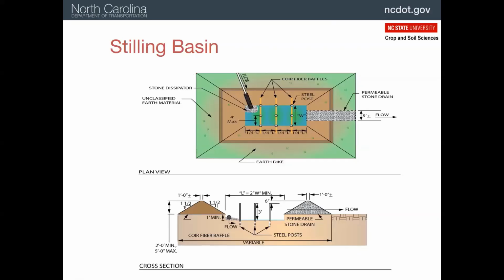Bird's eye view, so we're pumping the water and making sure that that is also released so it doesn't erode the inside of that stilling basin. And then we have an over excavation, so it's a foot deep here. So the water has to rise up a foot and then goes out through the stone. So that's our stilling basin concept. So it's essentially a simplified version of a skimmer basin.